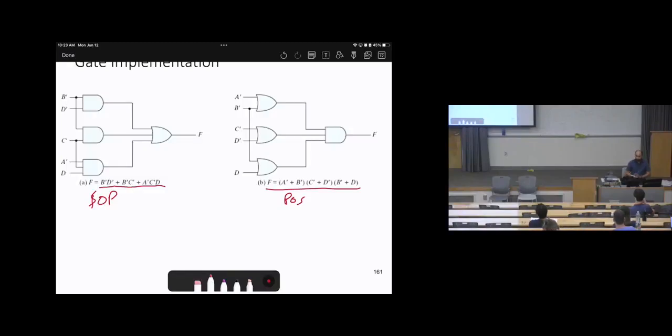Then how can we deal with this function, or how can we implement the logic gates? In my own design, I convert the problem into variables, then make the conditions, create a function. If the function was not simplified, find the canonical forms, do Karnaugh maps. So the overall problem gets shortened to get this function. This is my final result. In the previous two lectures about Karnaugh maps, we used to get the function. Now, how do we manipulate the function into logic circuits, so we can build my design.